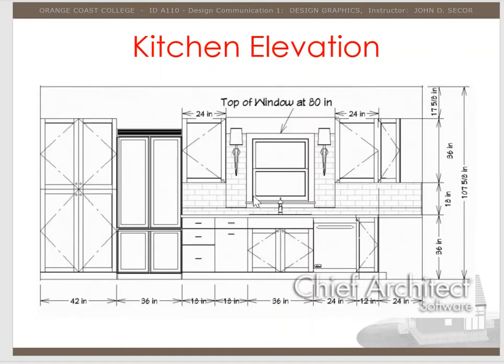Often we'll design the backsplash of the tile, and we can get more intricate the larger the scale of the drawing. And once again, always dimension on kitchens in inches. So I do love this particular elevation because it really has some nice detail. I just want to point out to you that the darkest line is the floor lines, and around the walls, and this has a soffit, some kind of dropped element. So it's dark. Then you get lighter.